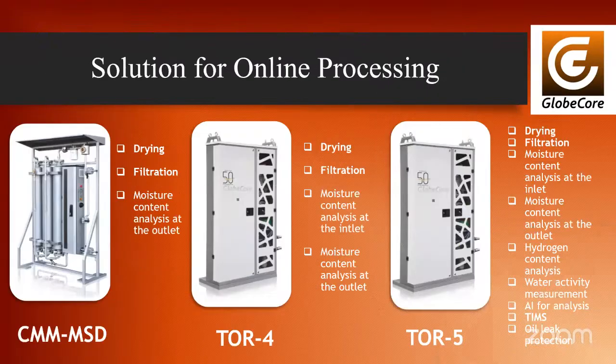GlobeCore has developed online oil drying and analysis solutions such as CMM MSD, TOR4, and TOR5. These systems can operate while the transformer is energized. Their main task is to maintain low moisture levels inside the transformers.